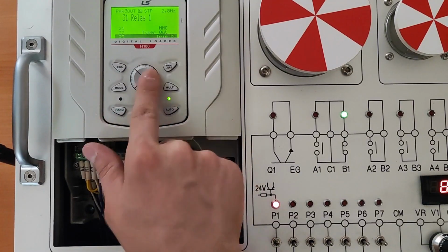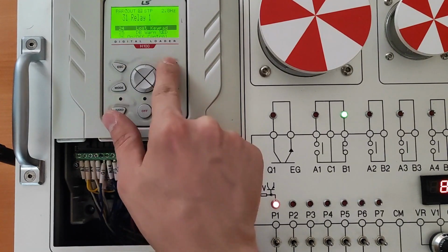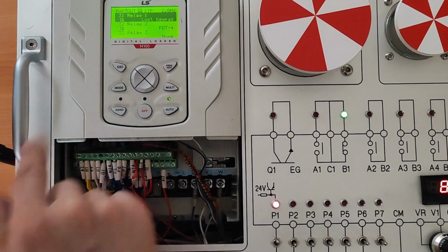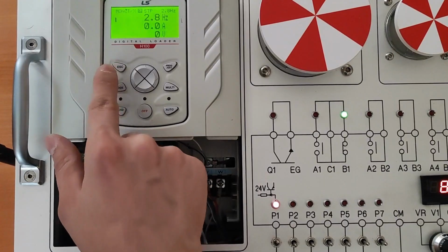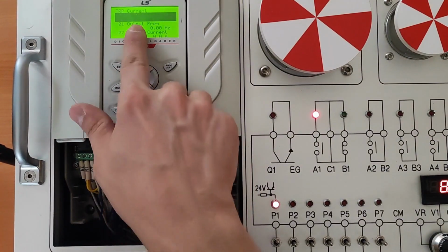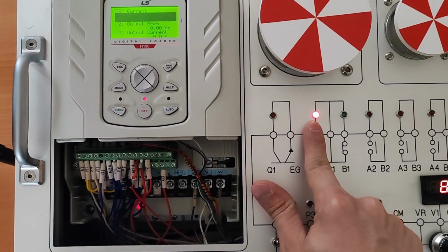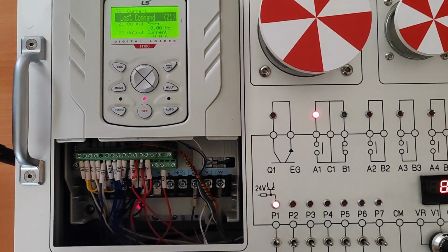We can then set it to the loss command mode, and finally exit the menu to ensure all settings are saved. Now, if the loss command error happens again, my relay number 1 is activated. You can see that it gave the loss of command error message, and since I had set relay 1 to the loss of command mode, relay 1 was immediately triggered as expected.